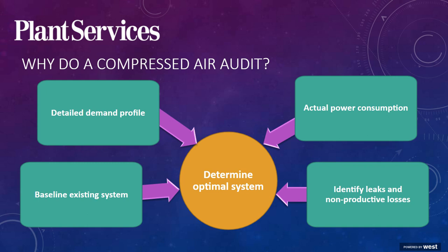An air audit from a competent compressed air professional is a first step in determining compressed air efficiency. And combining this audit with a leak detection service, as well as evaluating each air user, will improve overall system performance.